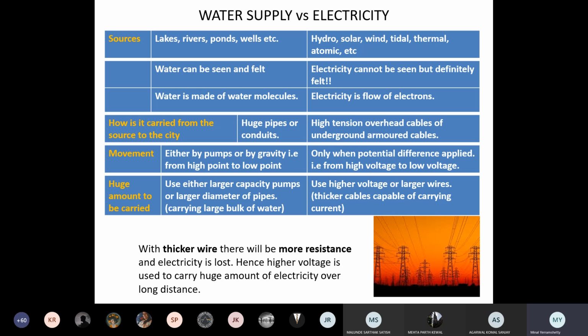And they are armored cables. Armored in the sense that they are highly protected and insulated. There is a metal sheath around them which helps the conduits to be protected. Because when I'm taking it underground, God knows what kind of heavy vehicles and what kind of digging can happen, where it can happen. There is no control over it, and we have experienced that digging in Mumbai, right? Anything can start anywhere without anybody's notice, and that can be detrimental for services lying underground. So to protect that, we have armored cables.